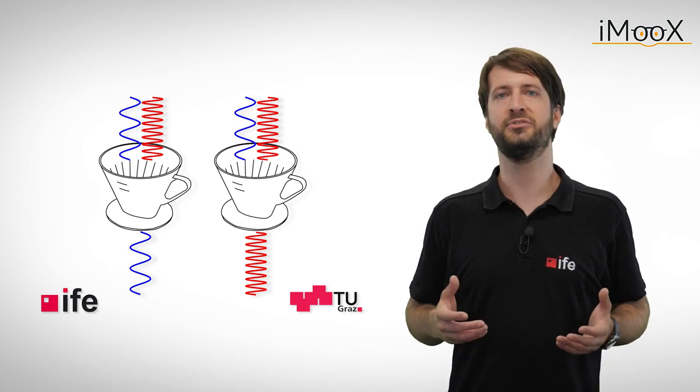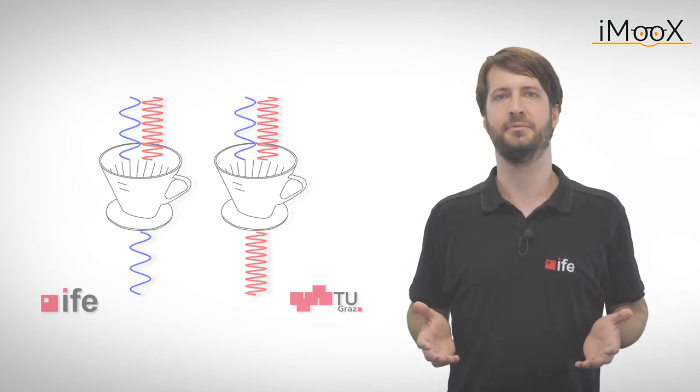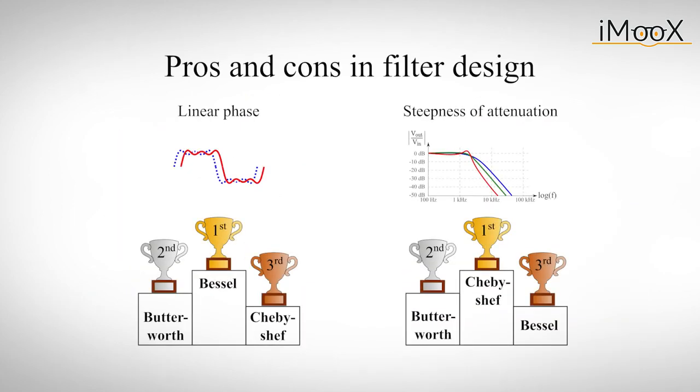Finally, you can choose the filter characteristic. If linearity is an issue, a Bessel or maybe Butterworth filter is needed. If steepness is the major argument, Chebyshev will save the day. One might also think about component tolerances or even temperature variation, which can have quite an effect on the real-world circuit.